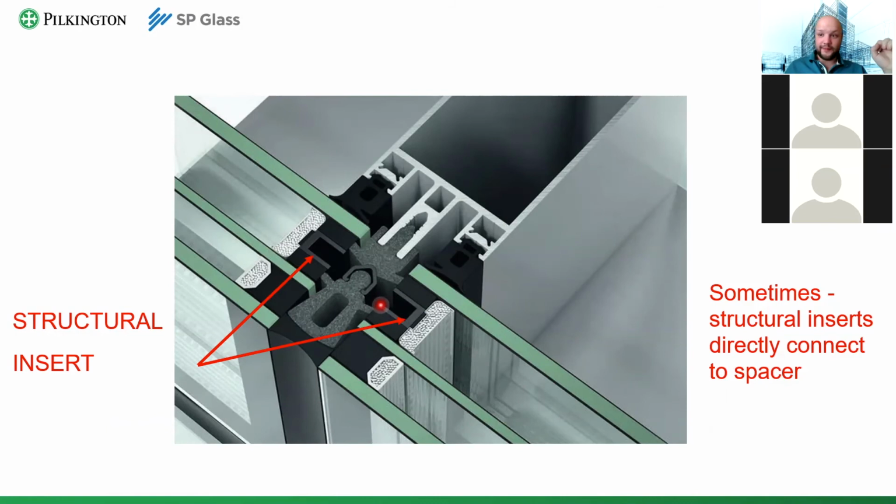So different design, different spacer, different depth. Again, I'm stressing this, it is very important that the secondary sealant depth in the case of structural glazing should be properly calculated all the time. And it should be done by professionals, those who know which loads to take into account.